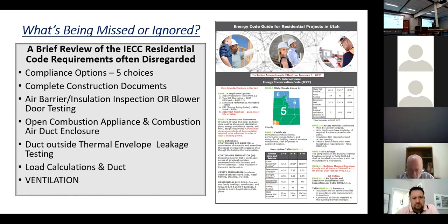So if it's 140 in the attic, 75 in the house, our temperature difference is 75, is that right? 65? Thank you. 65 degrees. And heat flow depends on 2 things, right? Temperature difference and insulation, right? Those are the 2 factors. So we have 65 degrees of delta T or temperature difference.